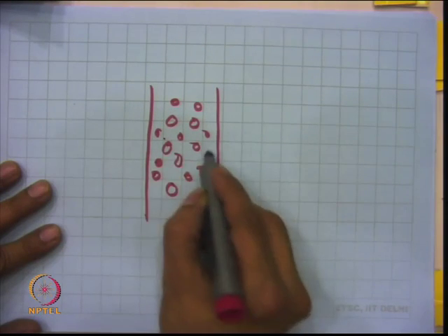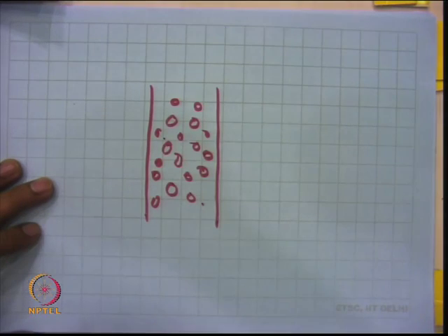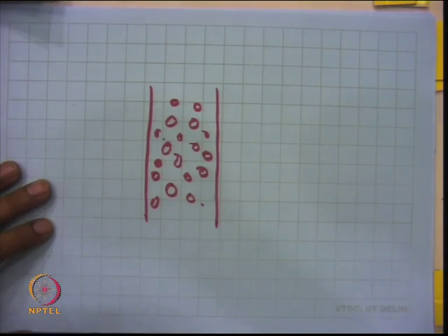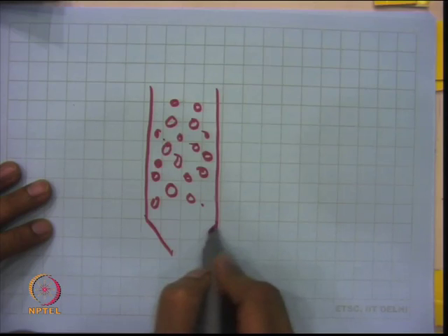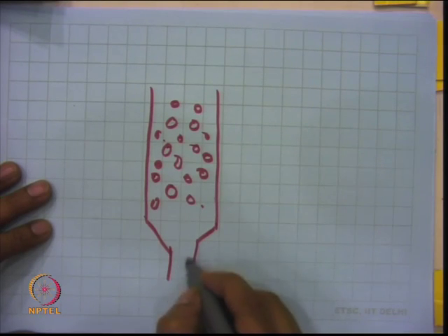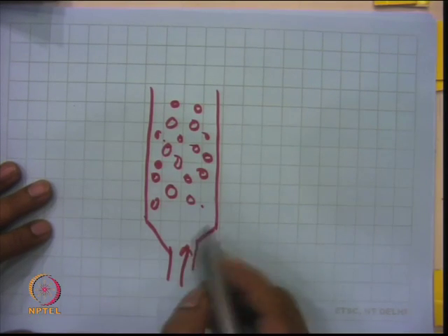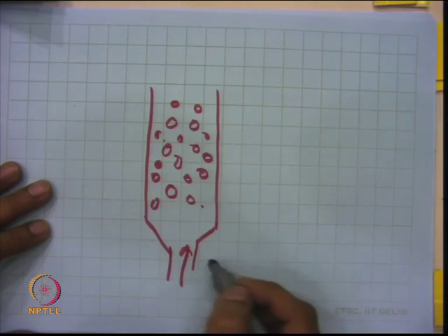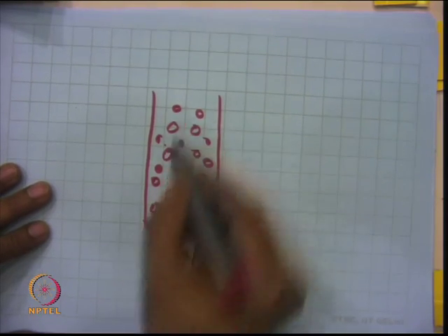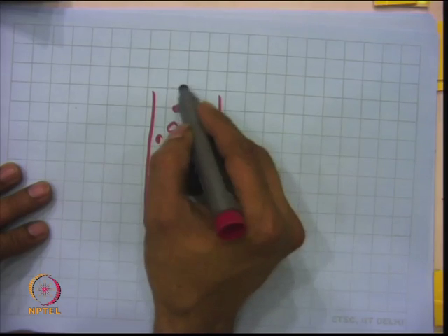These particles are something like your catalyst, just like the simple example of FCC, fluid catalytic cracking, and then you pass the gas which is a reactant gas. This can be your atmospheric gas oil or naphtha feedstock, hydrocarbon vapors, and then they pass through the bed, and you continuously have a product.